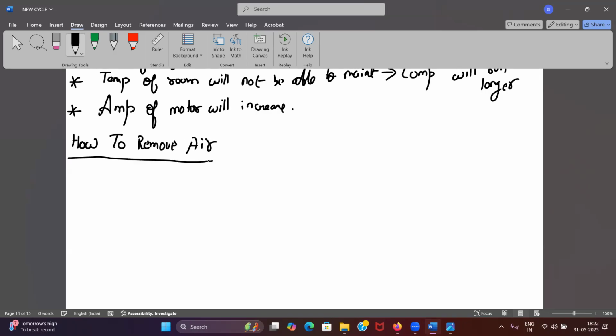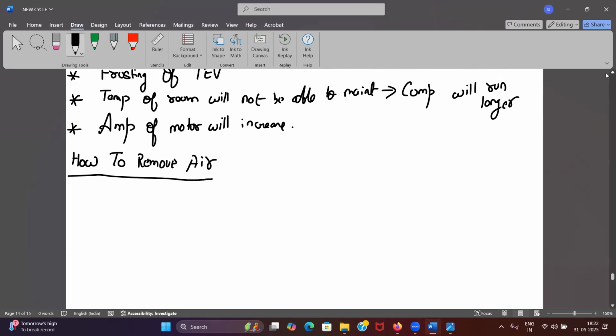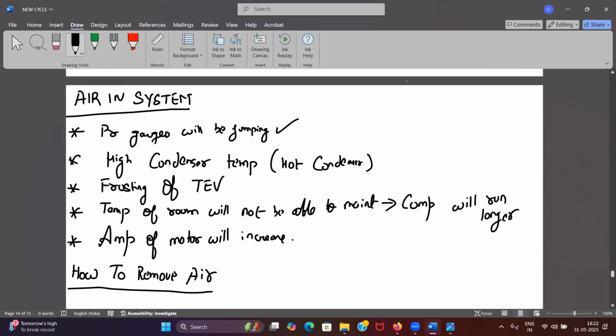Normally, sometimes surveyors also ask how you will know that air has come into the system. You can also say, sir, pressure and temperatures will be more in my compound pressure gauges as compared to what we have seen previously. The normal rounds you take, what are you checking in your reefer air compressors?